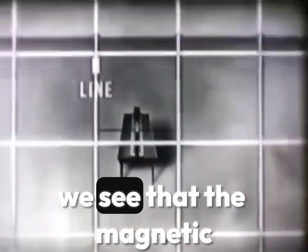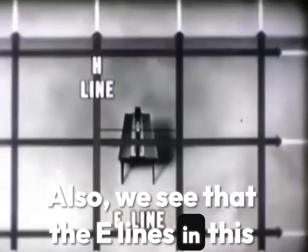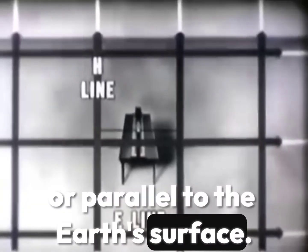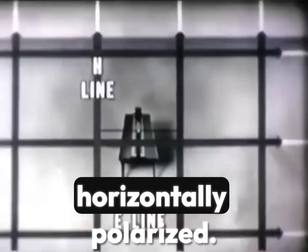For instance, stopping the wave, we see that the magnetic or H lines are still perpendicular to the voltage or E lines. Also, we see that the E lines in this wavefront remain horizontal or parallel to the Earth's surface. Because of the direction of the E lines, we say that this wavefront is horizontally polarized.